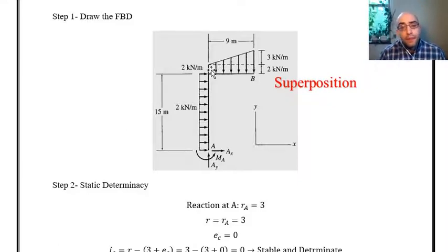And then I can say these two loads are working together and adding to each other in terms of the loading that we have on this portion of the frame. This is called superposition. The rule or the theory of superposition tells us that we can apply loads in separated amounts in a way that the summation of those separated amounts is equal to the total load that we have on the structure.